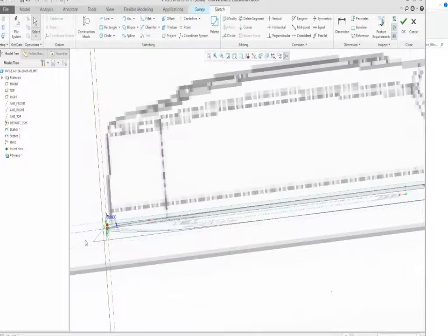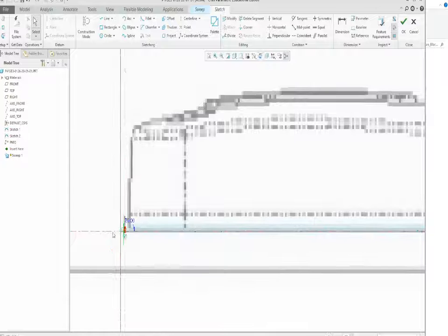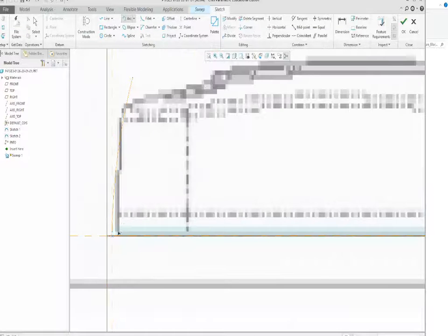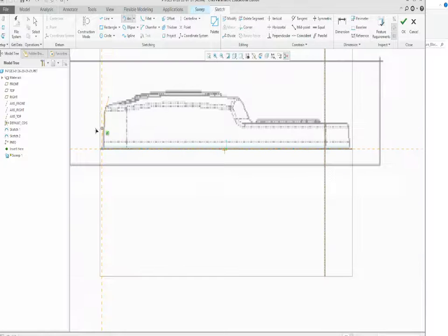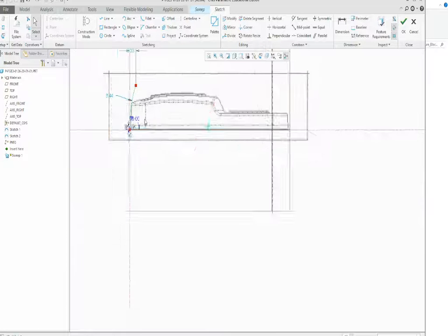Now we've got to build the curvature that we want for the profile. So now we go sideways so we can see it, and then we build the arch curve. I'm just going to do an arch curve off of the end of this and then pull up. You can see the tangency that it's creating for the profile of this design. And it's remaining tangential down here on that edge of that little line. So let's go with that. We want it to be high. So if we pull in a little bit right here, we can pull up, and we want it to be nice and high. So we'll pull higher than what we have on the profile here.